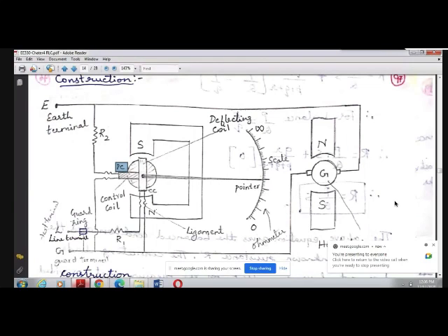Okay, so the potential coil will be connected in parallel. When the watt meters are shown to you, you will understand. The current coil will be connected in series with the meter actually. So there will be two coils here, one is the potential coil and one more is the current coil. Here this potential coil and the current coil will be connected to the spindle. As you have seen, this is the spindle that we are going to use here.